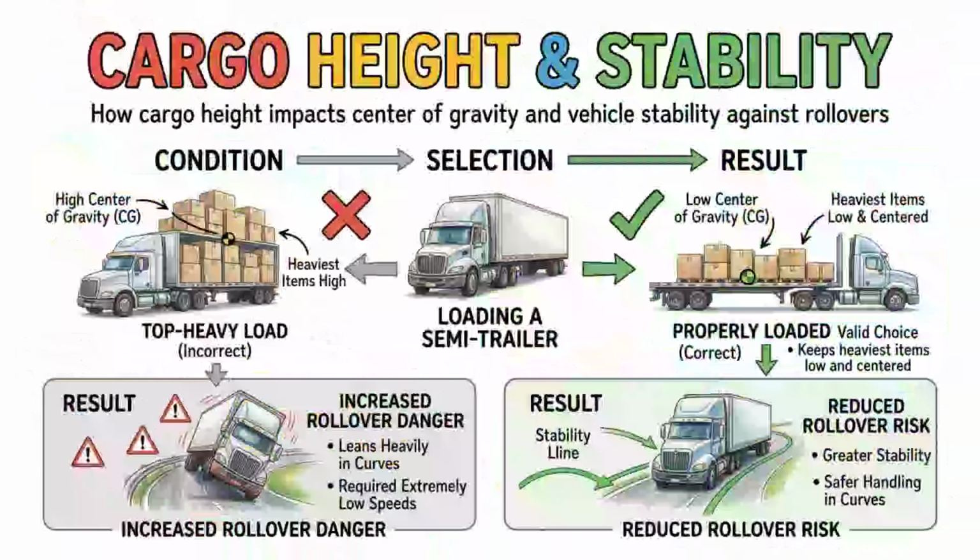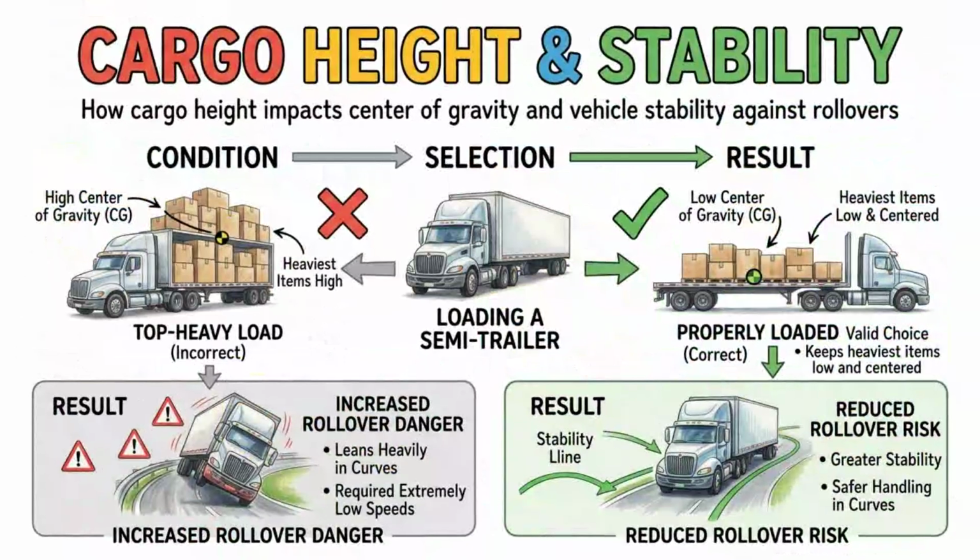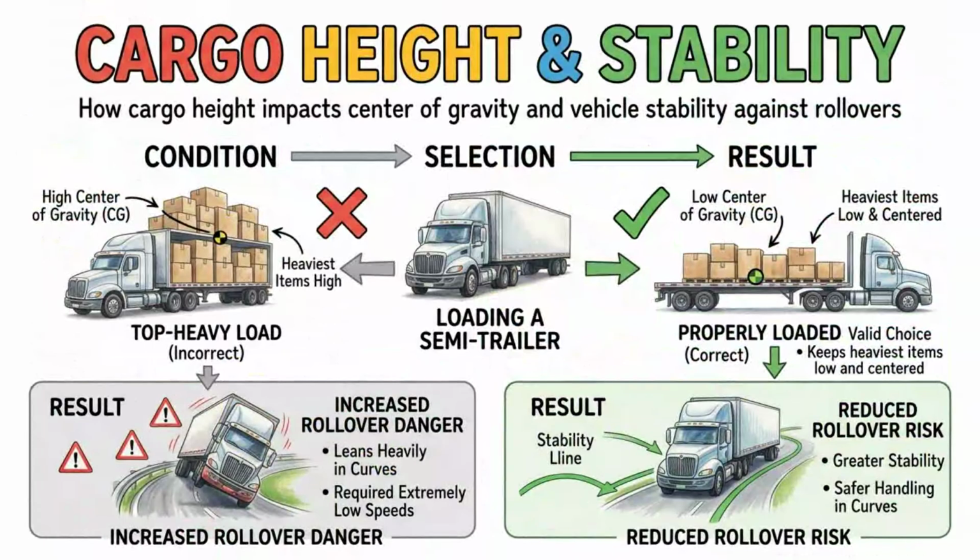Driving a bus requires extra caution around railroad crossings, which is one of the most strictly tested rules for passenger vehicles. By law, any commercial vehicle carrying passengers must come to a complete stop before crossing railroad tracks. You must stop between 15 and 50 feet away from the nearest rail, open your forward door and driver window, and actively look and listen for approaching trains. You can never legally shift gears while crossing the tracks, because if you miss a gear and stall the bus, you will be stranded right in the path of a massive train.